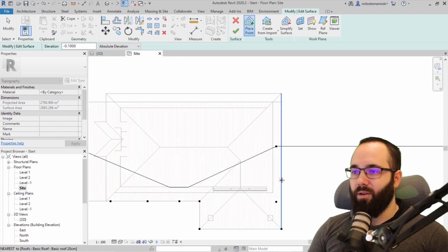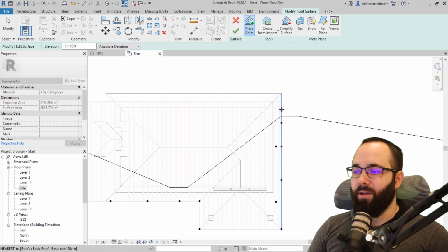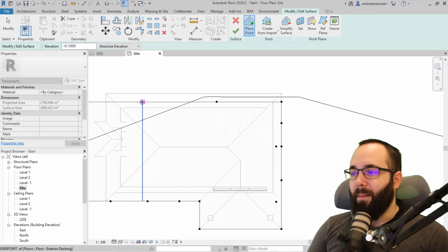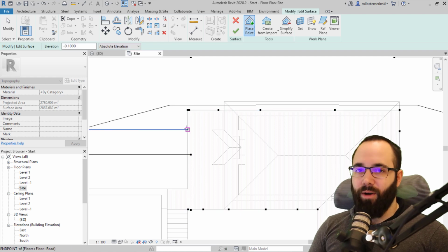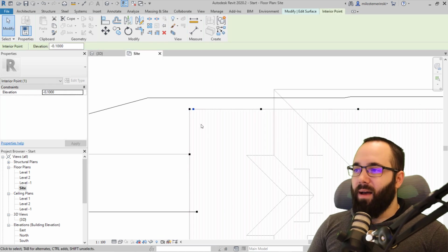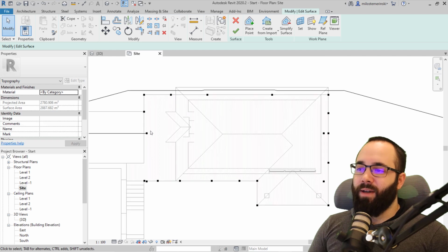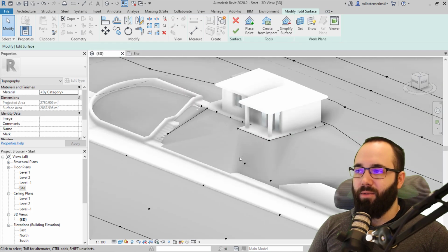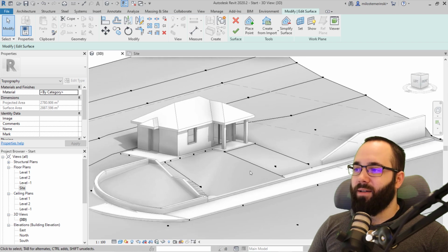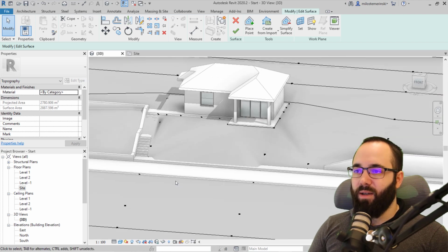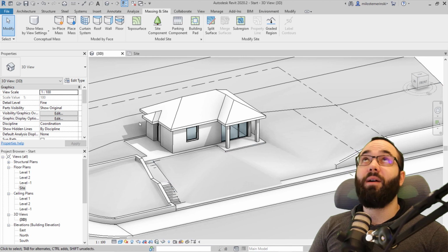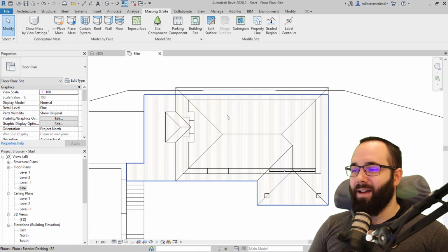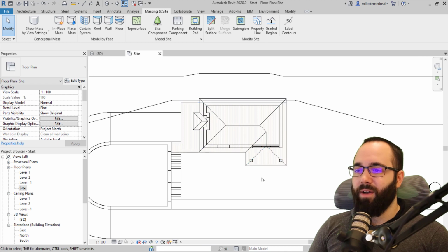And now when I go to the 3D view, as you can see, it's starting to look a lot better. Also, something that you can do, and what I like to do, is when I'm working with typography, because most things you're going to have to place in the site plan, but then you want to see that in the 3D view, so you can just undock the 3D view here and then perhaps dock it off to the side, so you can have that 3D view there above, and you can have the site plan here, so you can work at both.